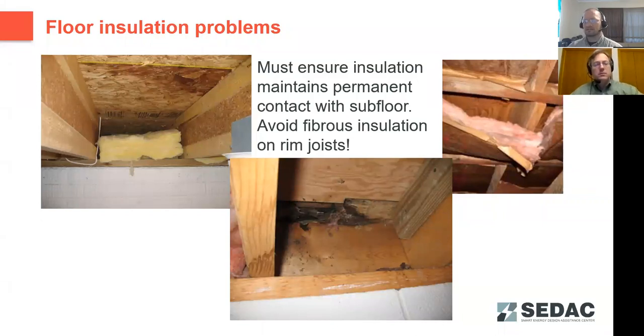Very important that insulation is airtight to that rim joist to prevent condensation from getting behind. Say fibrous insulation is common. If condensation can get behind there, that's going to degrade that wood, rot it out. You're going to have long-term issues with durability of that rim joist.